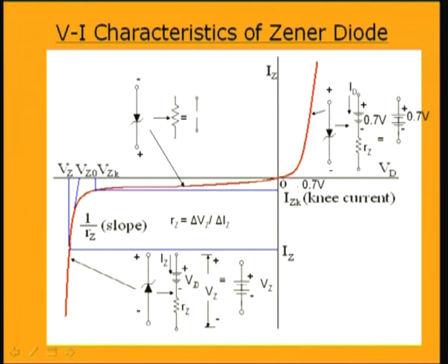So, now when the reverse bias voltage is low, even in the case of increasing the reverse bias potential, the current will be low, because this current, which is the saturation current, is due to the minority carriers only. So, the current is very small, and in this region, even if you go on increasing the potential, we will not be getting a rise of current.